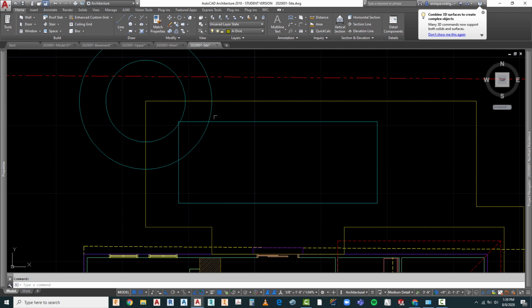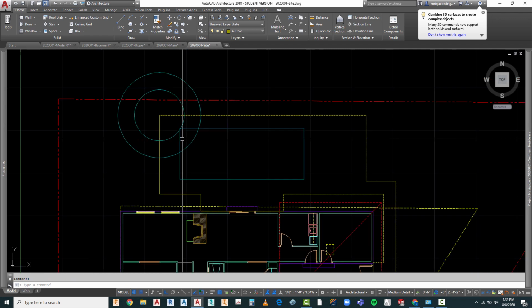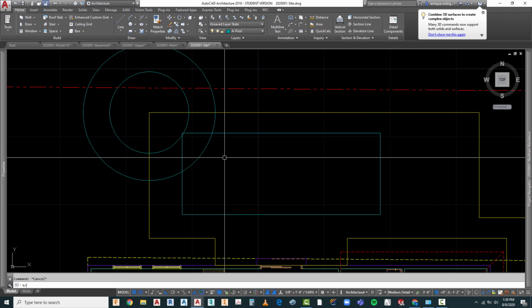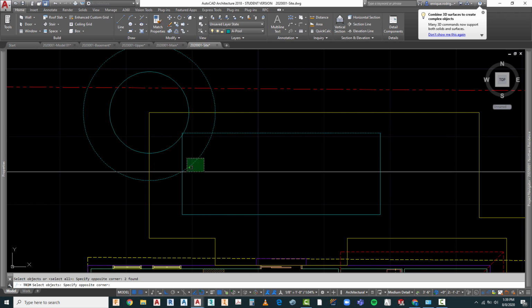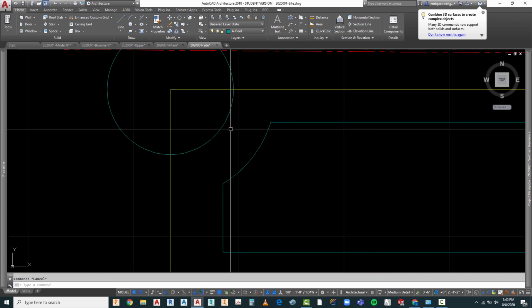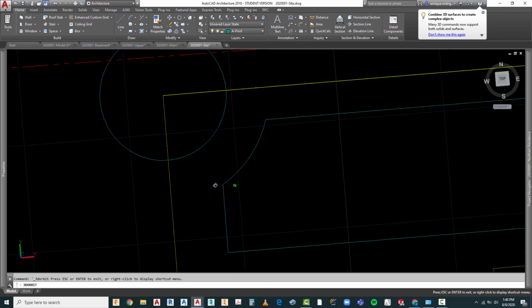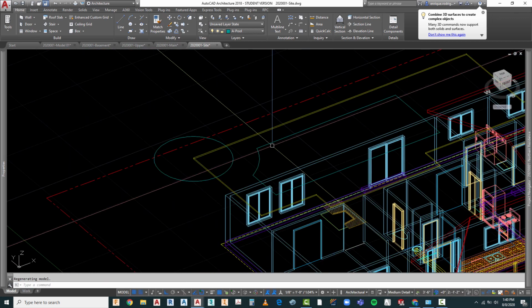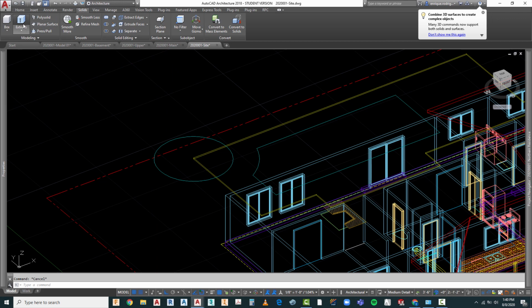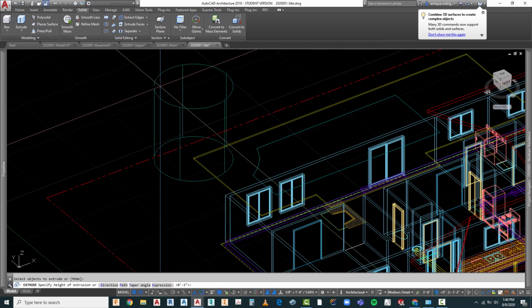Now this right in here is a 3D solid. So what do I do to fix that? Now I shouldn't have any problems trimming away my pool deck area like that. But this presents a little bit of a problem. So I'm going to go ahead and 3D orbit this. And I'm going to make this very simple. I'm just going to go to Solids, Extrude. I'm going to use the Subtract command. Now I can bring this up as high as I want to.